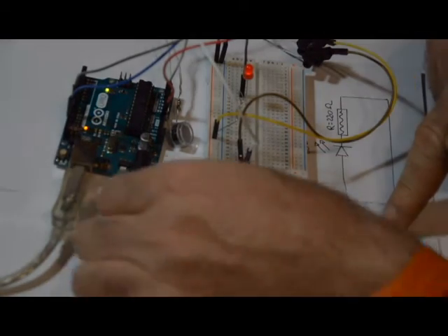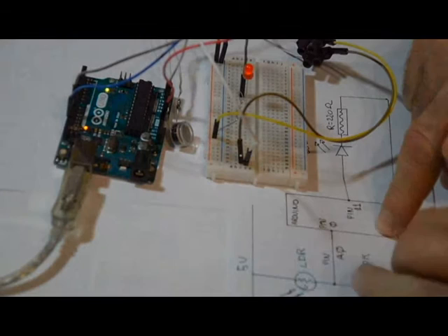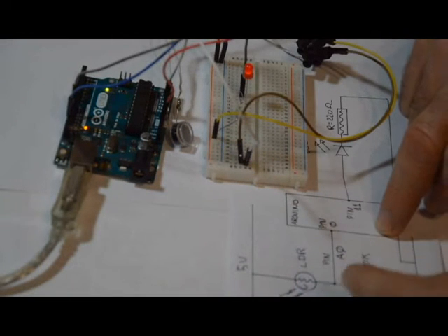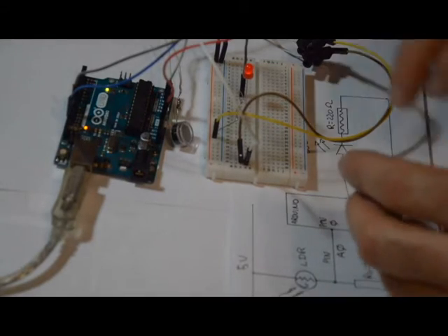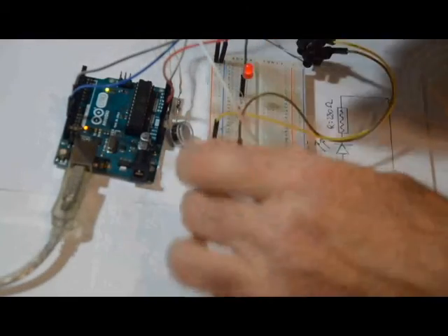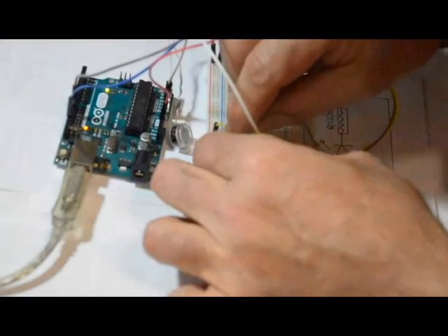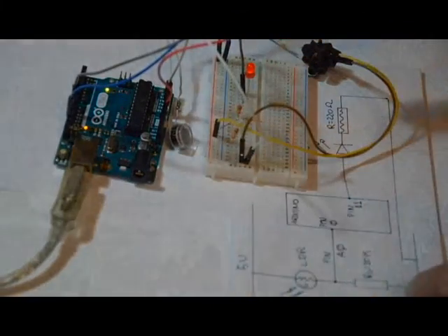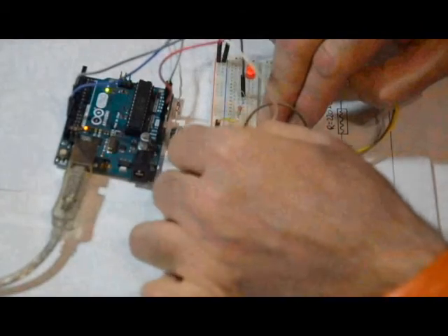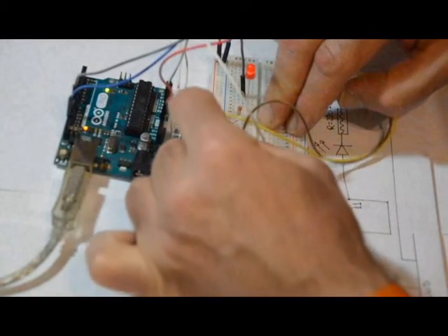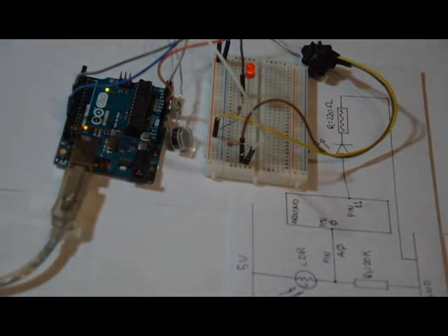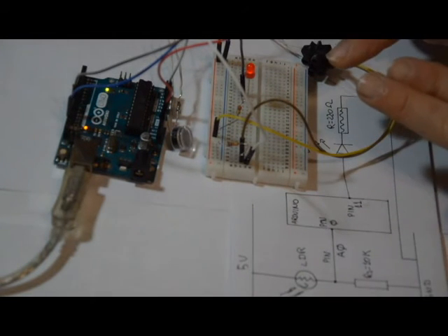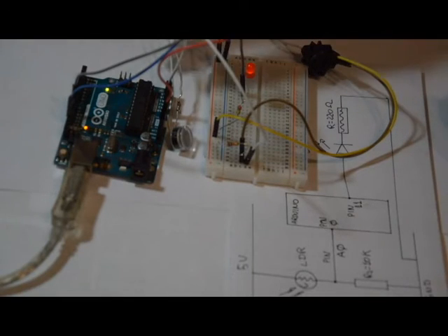And we have to make the connections for the other resistance in the voltage divider. So we connect one terminal to the resistor, and the other terminal of the resistor has to be connected to ground. So this is the ground level. That's it. So we have made all the connections, and let's check if it works.